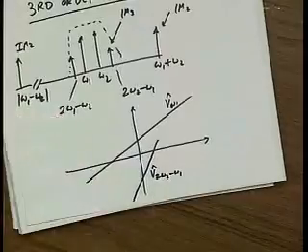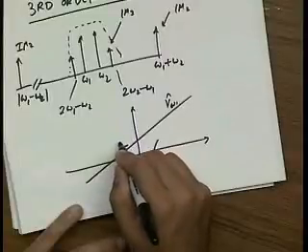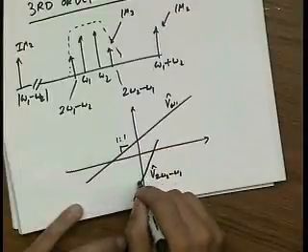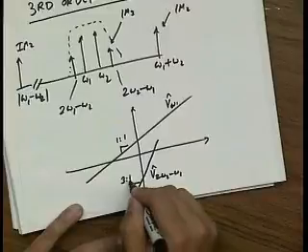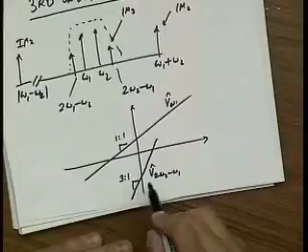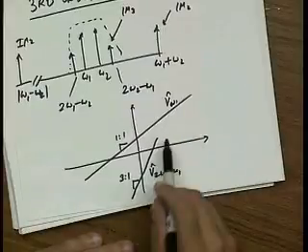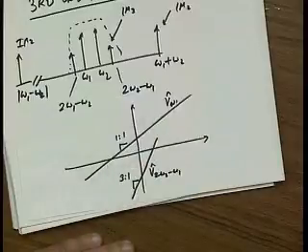This is the amplitude of the third order. And now you'll notice that if the slope here is 1 to 1, the slope here is going to be 3 to 1. That's because we know intermodulation goes like the cube of the signal. So this IM tone catches up very quickly because it's moving 3 times as fast on a log scale.